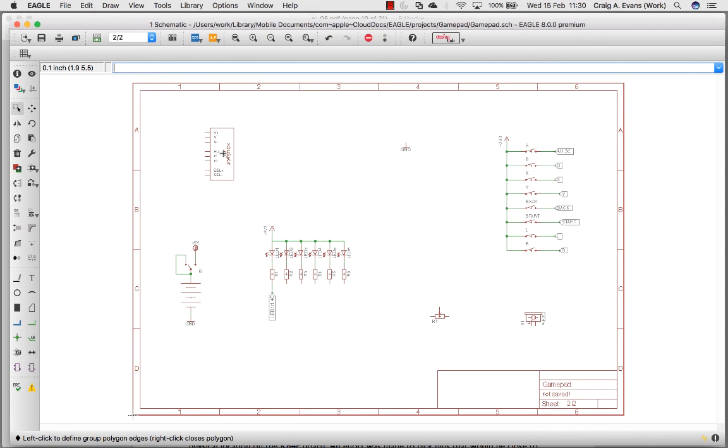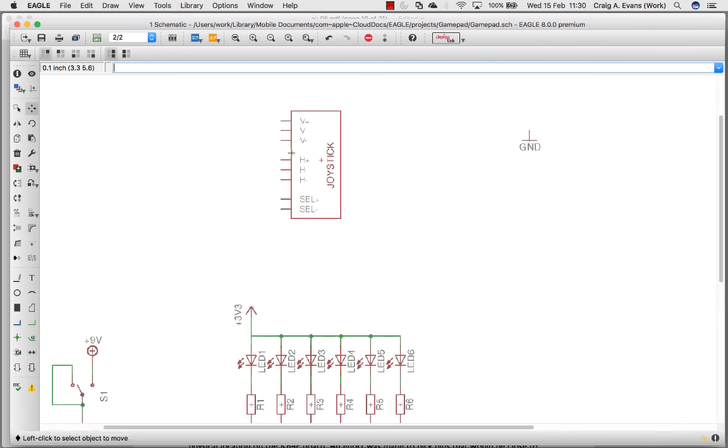So the joystick, we now set up the joystick. So we're going to need the 3.3 volts for that. So I'll just copy this symbol. So I'll just copy these. So that's the horizontal pot, vertical pot. Again, add a junction in there just to stop it moaning. And the ground symbol, move this. I'll just put this down here.